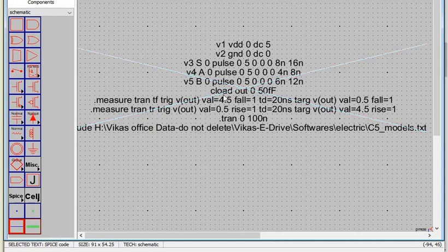And then this is my load capacitance, which I have taken between the output terminal and the ground. So 0 indicates the ground level, and I have attached an assumed value of 50 femtofarad. By changing this 50 femtofarad to different values, I can change the rise time and fall time of this entire output. So this plays a very crucial role. I'll talk about that sometime later. For now, you can just consider a minimum value of 50 femtofarad.